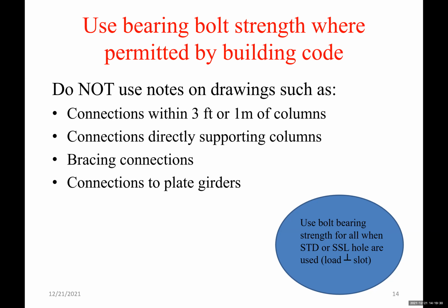And we have beams framing into girders. So avoid using notes like this. Bracing connections, okay? Take each connection and deal with it. If you're not designing that, of course, the connection designers or the fabricators are designing that. So all you need to do is just show them the forces, show them a typical detail, and they will design it, okay?